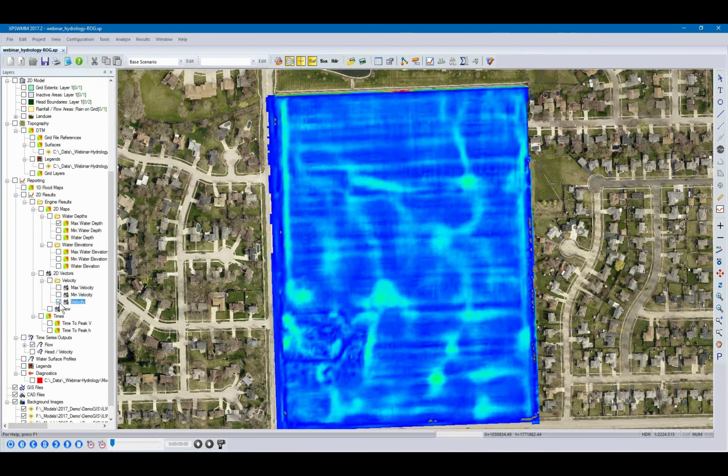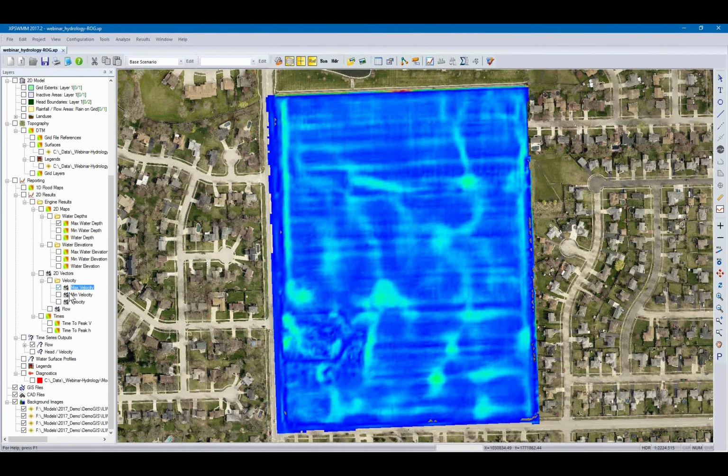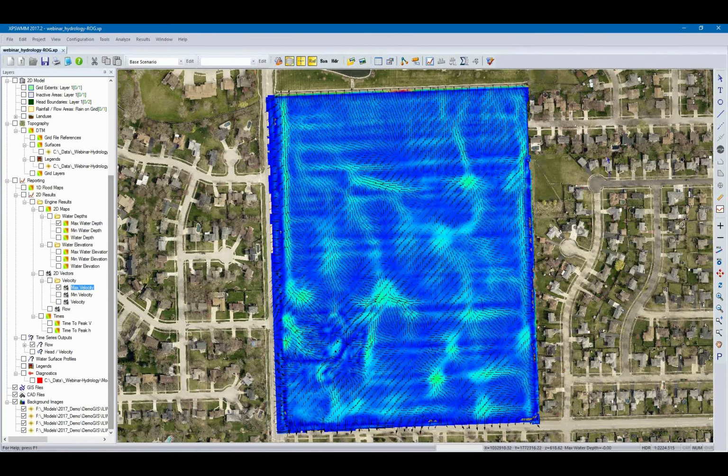If we begin to look at the velocity arrows, okay, and this will work much better probably on the adjacent elements in the urban area than a bunch of contours, I can actually begin to see where a minor subcatchment might come into play. And I can use these velocity vectors to help me divide, if I were to subdivide this 40-acre parcel into smaller subcatchments, I have that ability, okay?